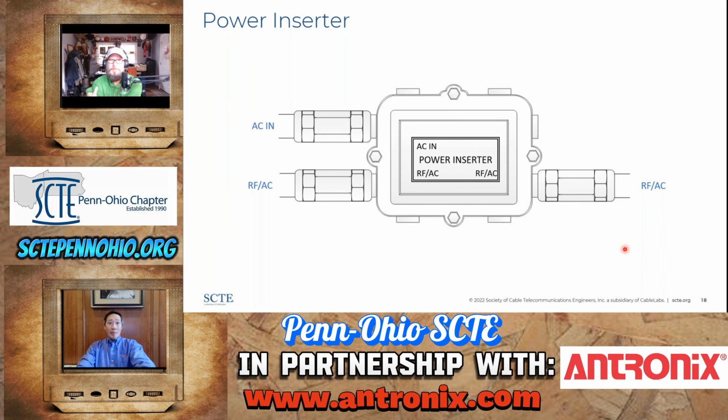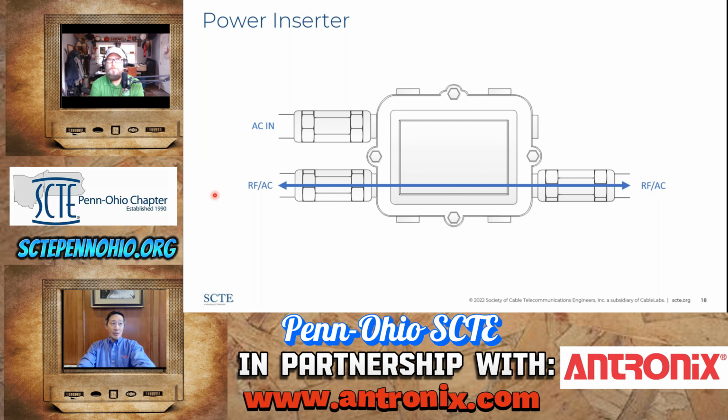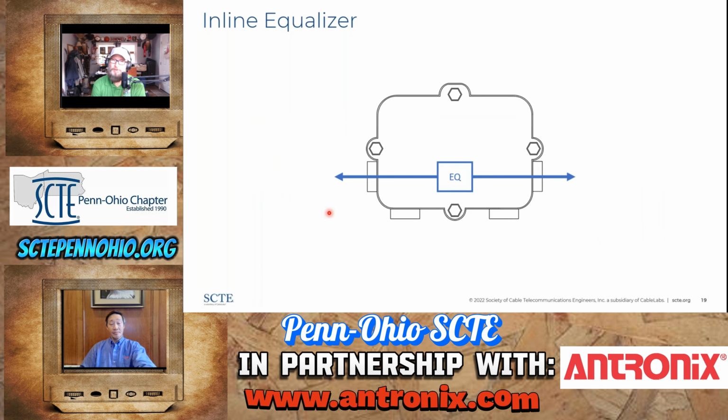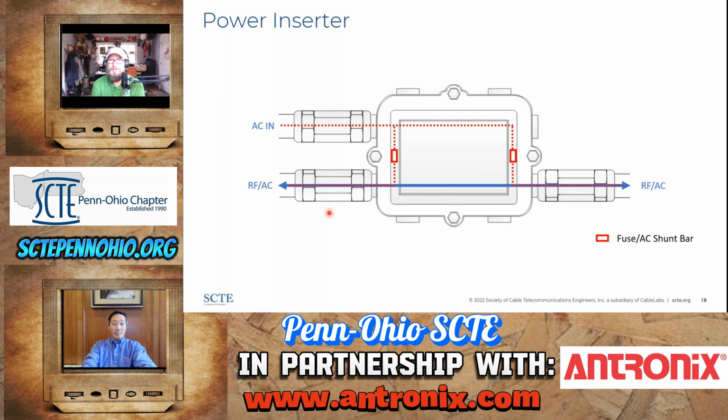Power inserter. Power inserter is quite simple. It has the RF going in and out, and it is really just combining the AC from an AC power supply to inject AC into the network, into the main line. This is also bidirectional. There's no direction associated with a power inserter. AC and RF can go in either direction. Very important, though, because if you don't have power, typically you don't have a network, unless, of course, you're talking about passive optical networks, but then you don't have RF passives either. So there's that.